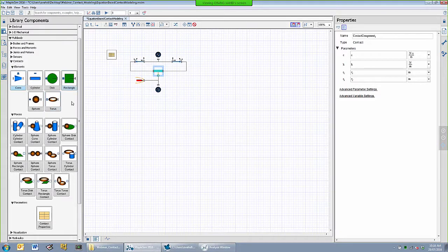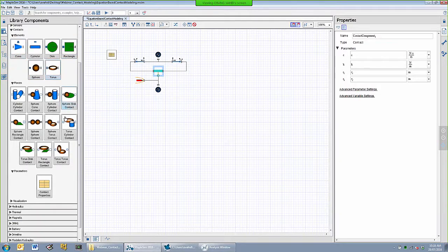Depending on what element is being used, you would select the appropriate contact force component. Unlike the simple example that we just went through, these contact elements will also include friction between the 2 surfaces, and we will see what other details they can provide to enhance modeling.